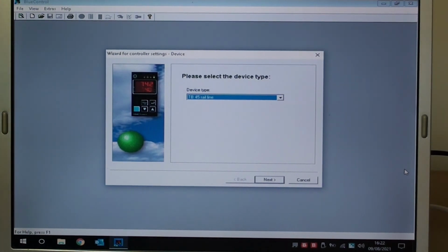Okay, so I have restarted the computer. That wasn't the issue, but I did find out what the problem was. With this particular device, you do need to power it to find it in BlueControl. Now, you could still discover it, the PC could still discover it and install the drivers, which is why I never thought to supply power to it, but it looks like if you want to communicate with it in BlueControl, you do need to power it up.